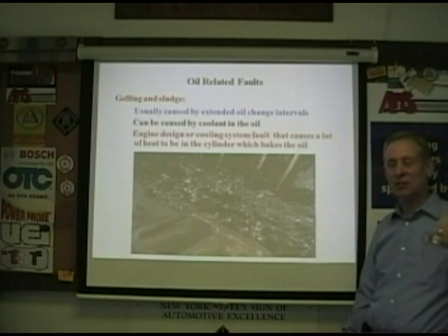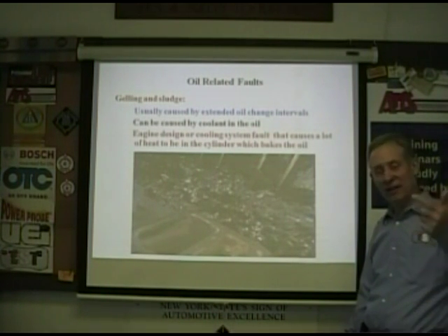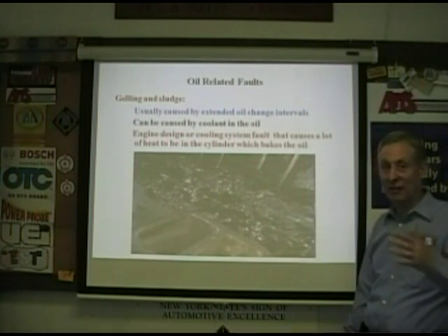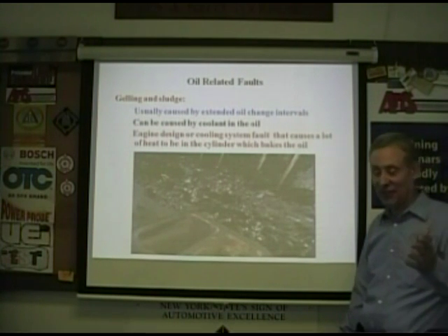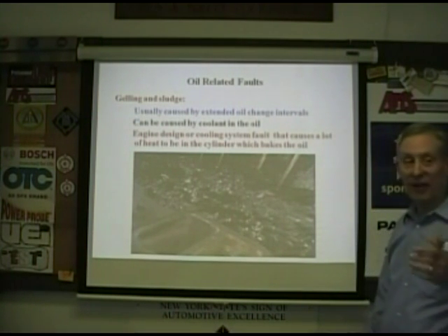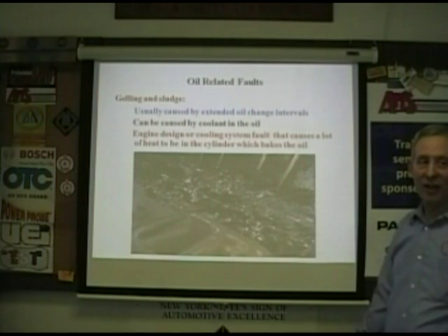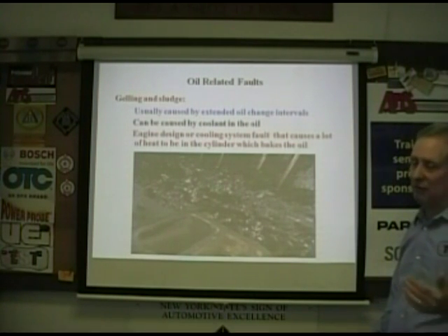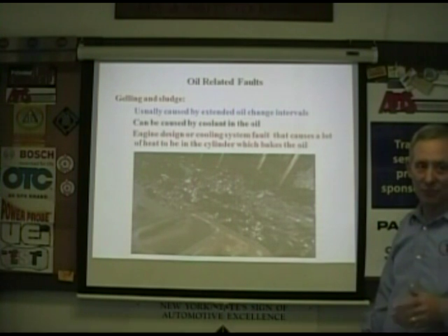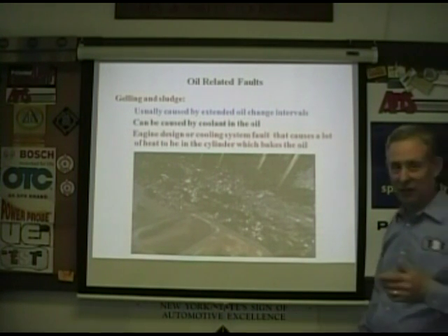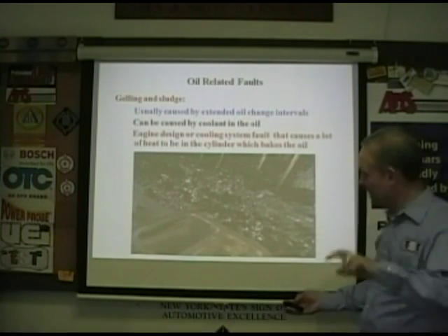Dirt was introduced, the wrong fluid was put in, not enough fluid was put in, whatever. They ran it kind of dry before it got filled up. They found over the fleet, over the life of the vehicle, that it was better to just have what they call lifetime fluid or non-serviceable boxes. In reality, they're controlling the lifetime of the vehicle.